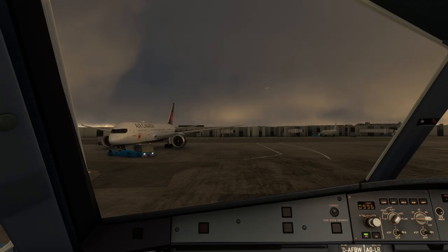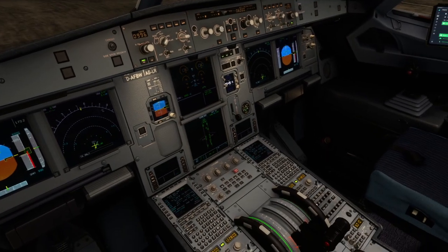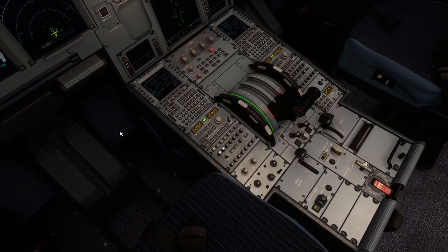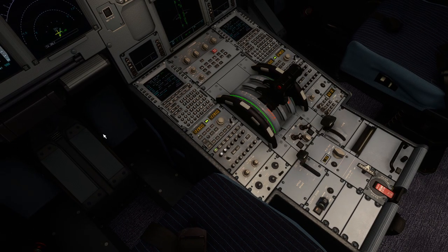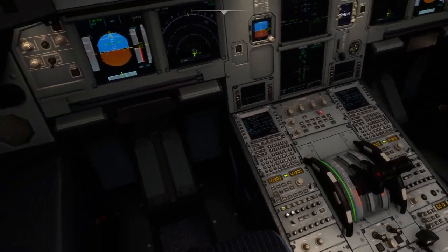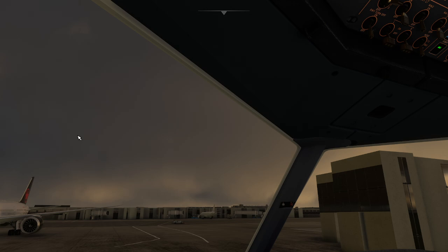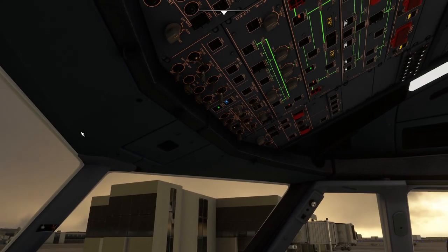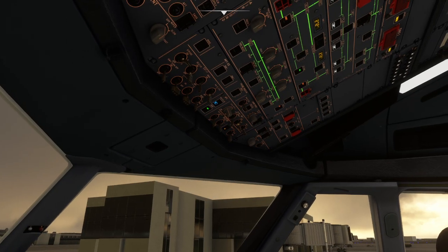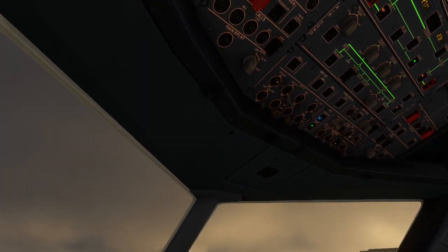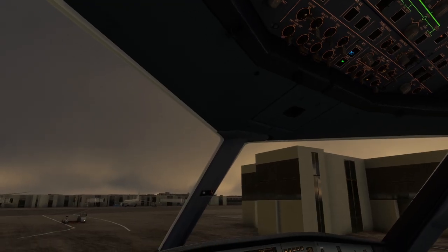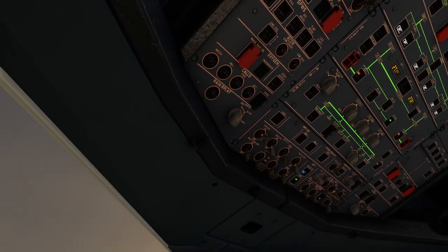Okay, let's go through the checklist. Let's get Heathrow started. Expect PDC. Parking brake set. Chocks connected. Throttle, thrust levers set idle. Engine masters off. Batteries on. Generators. Generator switches not turned on. Let's wait until engine started. ADIR is set. Panel display set. We're switching on.